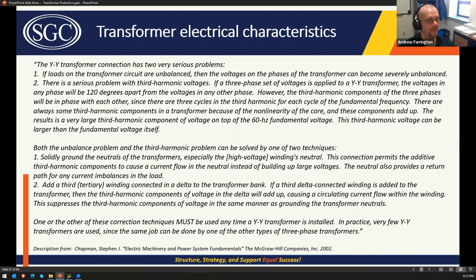So if you have a ground fault on the distribution circuit, you don't have ground overcurrent protection or ground differential protection operating on the 115 kV transmission line, because the Y winding on the 115 kV side is not grounded. So there's no path for that zero sequence fault current to flow through the transformer. But you have the source on the low side because of the delta tertiary.